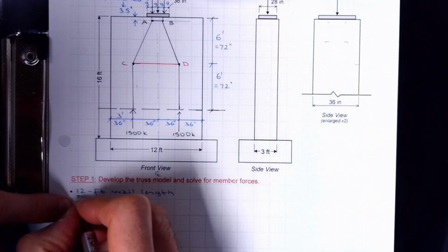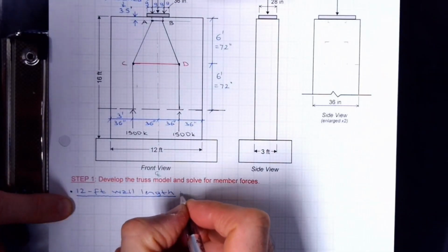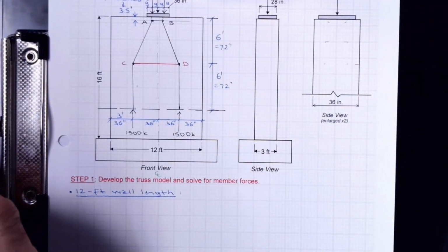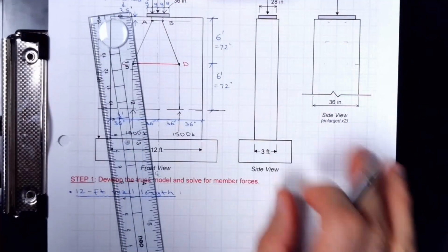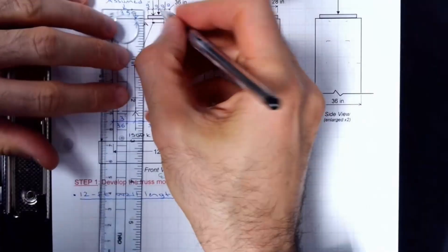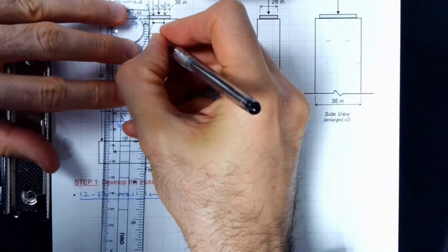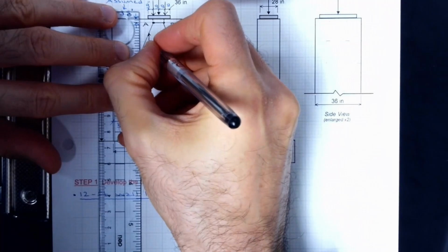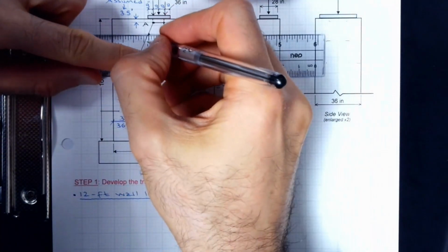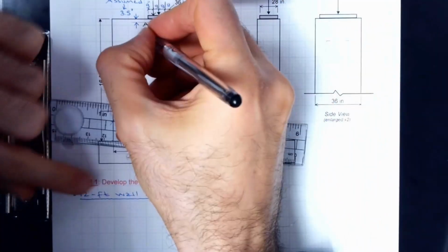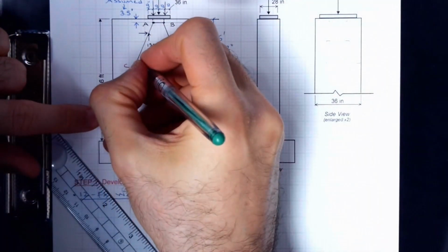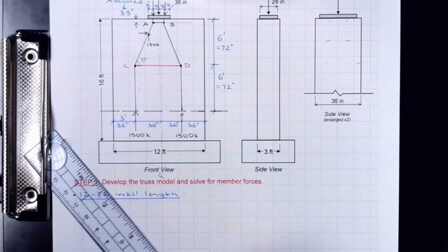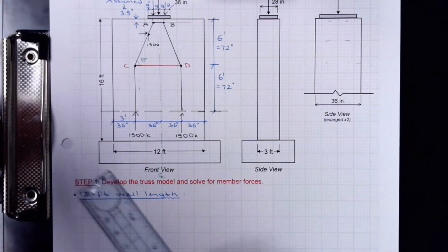So I'm going to be looking at compressive stress flow across the 12 feet wall length. I need to do a truss analysis, of course, to get this problem started. If this is 1500, this truss would have 1500. I'm only solving half of it because it's a symmetrical system. I need to determine this as well as the angle. The angle is, as you know, super important. The larger the angle, the more efficient the model will be.